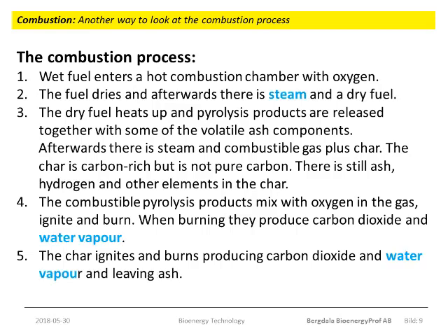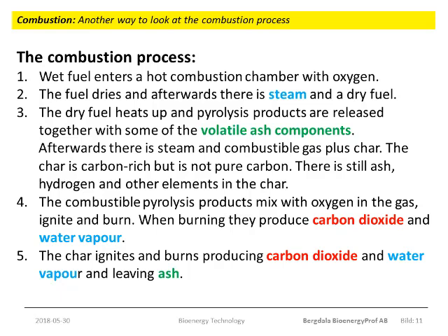So what is ultimately found in the combustion products, assuming a complete burnout so that there are no unburnt components left, is water vapor from the fuel moisture, from volatiles combustion, and from char burnout, plus carbon dioxide formed by volatiles combustion and from char burnout. When it comes to ash, it will be found in the gas phase as well as in the bottom ash.